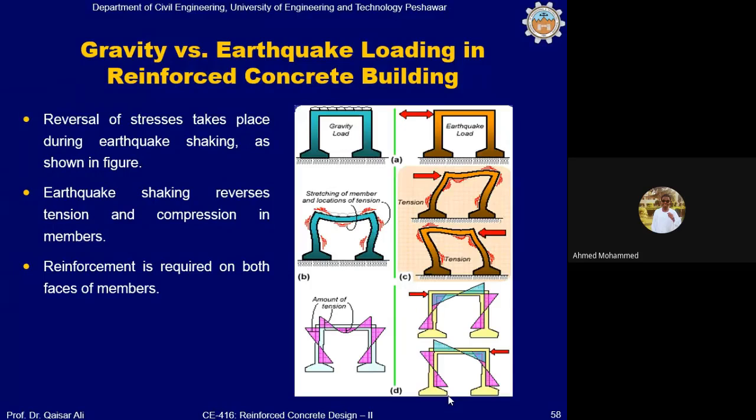What I know about creep is that it is a second deformation of the structural element. Yes, under sustained loading, not additional loading. Sustained loading means that if a load exists for a long time on a reinforced concrete element, then it will deform with time under this sustained load, not additional load. So this is the creep phenomenon.